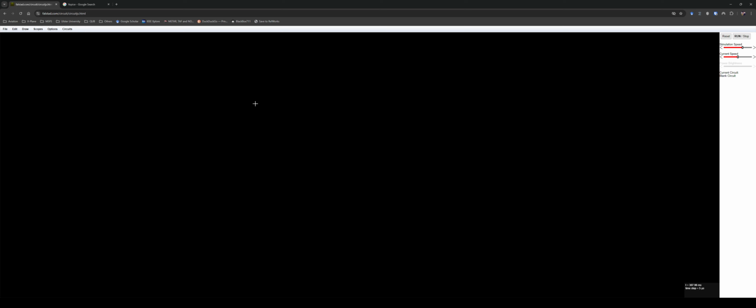I'm going to press V for voltage. You see now that I have a cross, and I'm going to drag, usually from bottom to top, to create our voltage source. If I double click on it, I can choose the voltage, so let's put like 20 volts. Although the voltages we're handling with the Arduino are a lot smaller than this, it's maximum 3.3 volts.